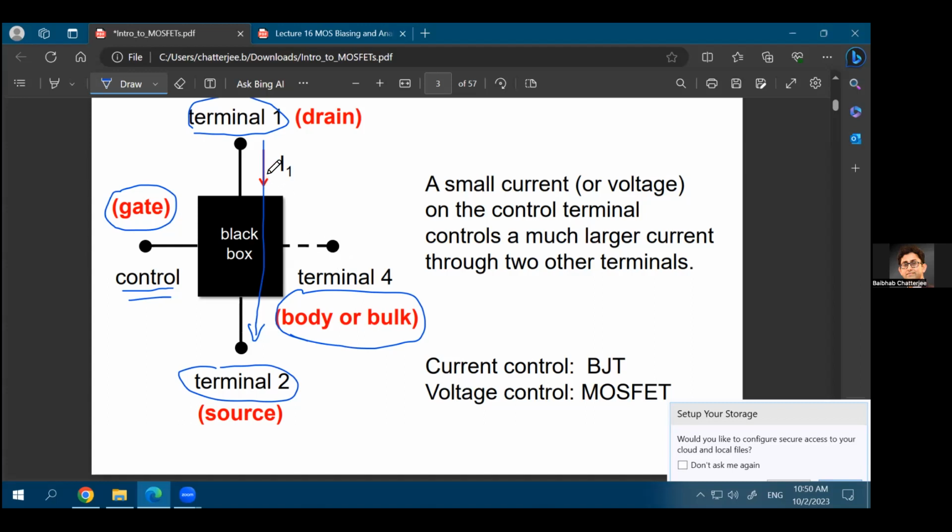So generally, you'll see that the books write that the MOSFET is a 3-terminal device. Then they're talking about the drain, source, and the gate. But if it says that it's a 4-terminal device, then you're talking about the body or the bulk as well. And it is also an important terminal of the device. Even though not as important as drain, source, and gate, it's important enough.